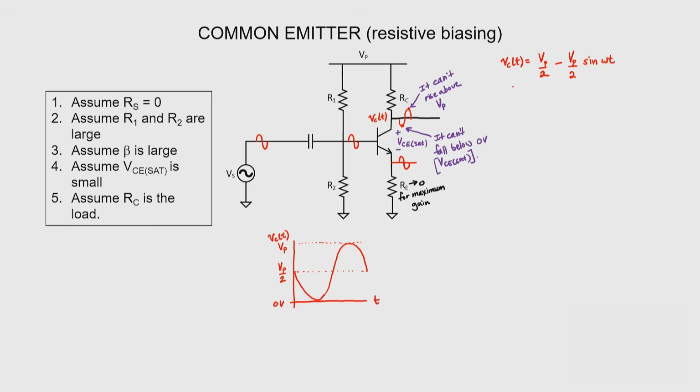I'm interested in calculating the efficiency. This kind of amplifier, where you have some DC component and AC component flowing into the load resistor, is called a single-ended amplifier. I'm interested in knowing how much of the AC power gets delivered to the load. I don't care about the DC offset in the load.